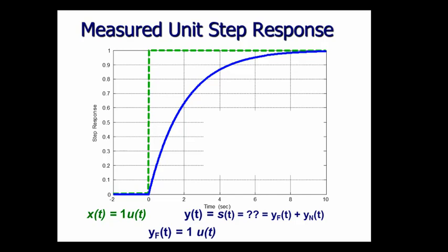How about the natural response? What shape is that? What kind of mathematical function does that natural remaining part look like? Exponential. And is exponential one of my choices for natural responses? Yes, it is. So it's got some exponential response. Some unknown k e to the alpha t. I don't know what alpha is. I don't know what k is yet. Can I get those from this wave shape?